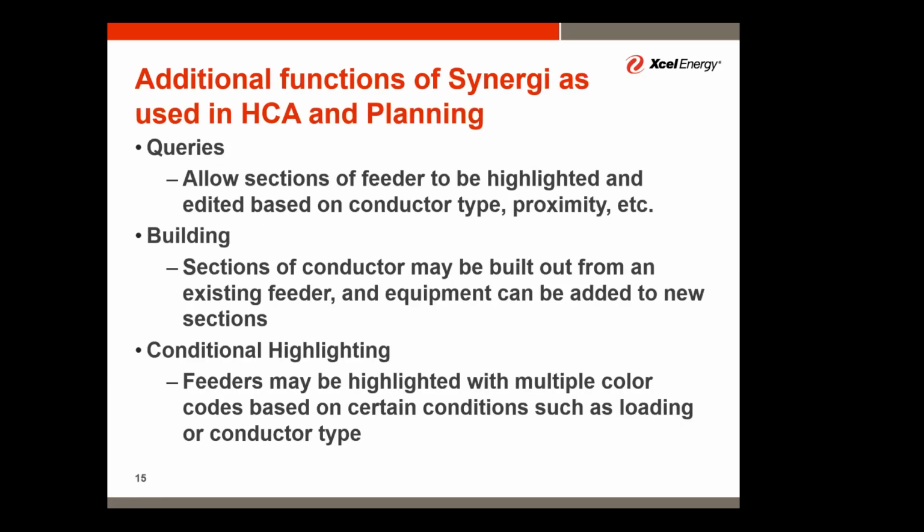So again, we'll discuss some of the additional functions. Like I said, queries are allowing sections of the feeder and conductor to be highlighted based on conductor type, proximity to each other. Queries may be held from an endpoint of the feeder and run back to the head end of the feeder if any edits are needed there. And essentially, it's a mass editing tool as well as a highlight tool to correct any issues or make any updates.